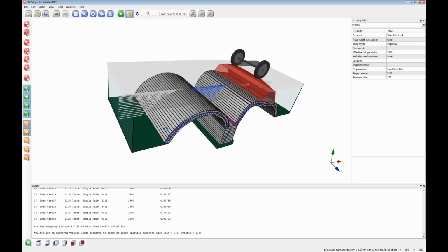Got a number of questions from one of the delegates. Where can I find appropriate material properties, sliding friction coefficients? Assessment codes are a good place to look, or alternatively, obviously design codes, although design codes, generally speaking, would suggest quite conservative values, for example, for the friction coefficient.